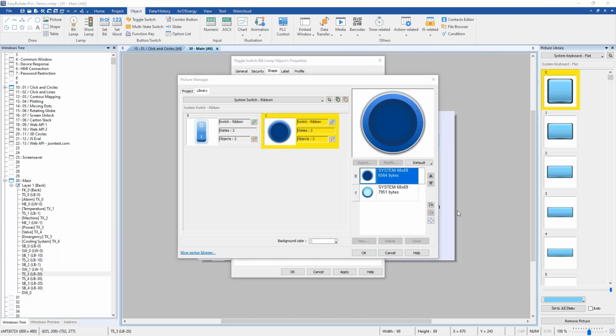If you're in a factory that has a lot of electromagnetic interference, many interference at the HMI site, you might need to use a resistive instead of a capacitive screen, because a capacitive screen can be easily interfered with, right? But other than that, I think the capacitive screen looks better and is smoother to operate.